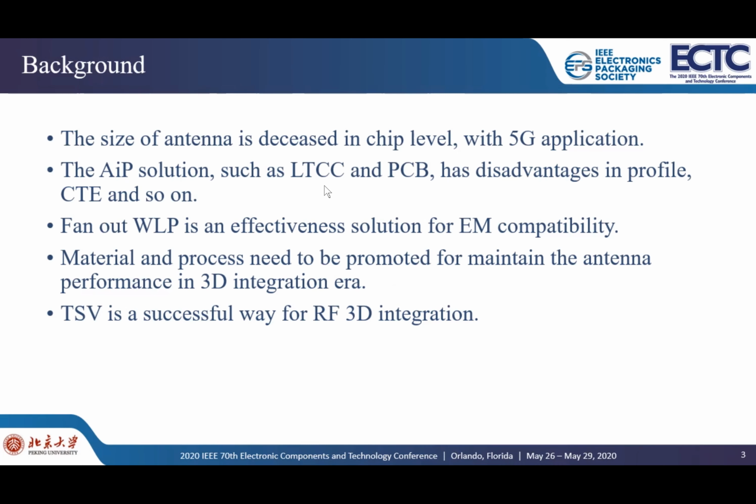Here is the background part. In 2020, 5G has come in our life. The antenna working at a higher frequency will have chip level size, so the antenna integration in chip scale is possible. The developed package technology like PCB and LTCC have disadvantages in size and precision.